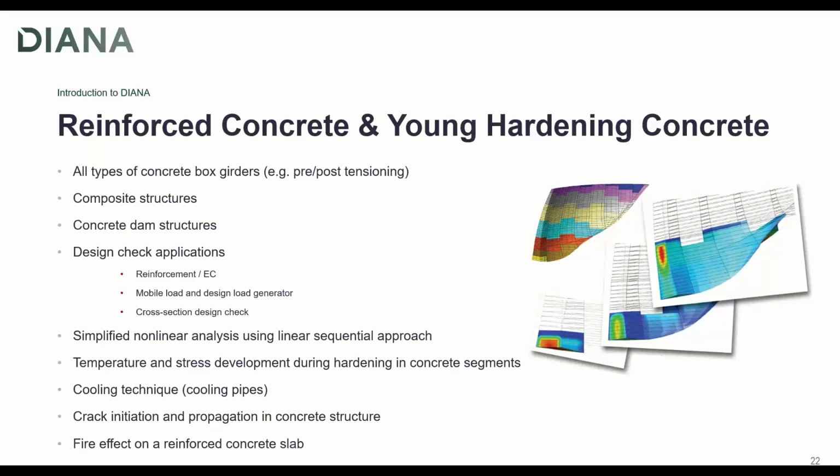Temperature and stress coupling let you analyze how the concrete goes through aging. Cooling pipe is also another powerful feature that we offer in both 2D and 3D in order to control the hydration process. Crack initiation and propagation in concrete is one of the powerful features in Diana, and also fire effect, how the fire could affect the durability of your structure.